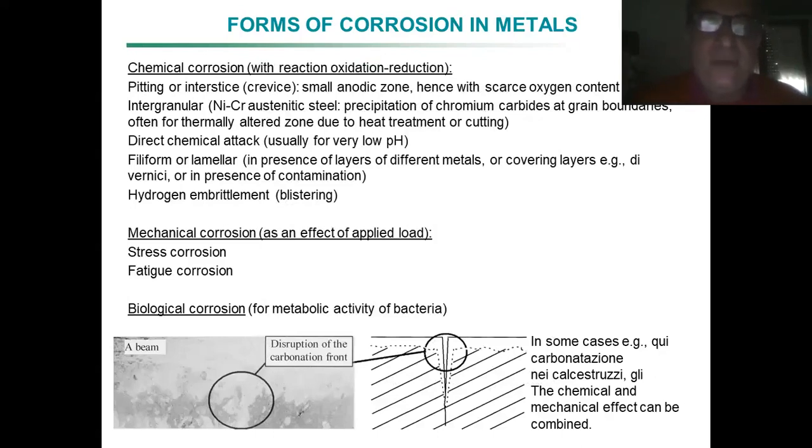As a consequence, these two metals, in some cases, tend to detach from each other. Also because there is a chemical effect: different metals have different abilities to be oxidized. Some metals are more easily oxidized than others. We say that they have different electrical potential.